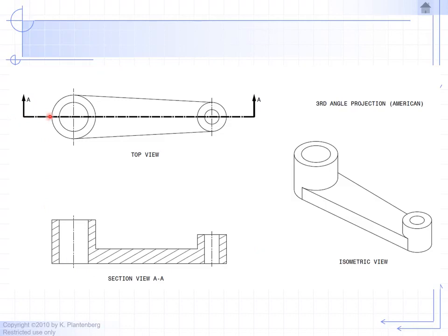And as you're cutting through the top view, here you're cutting through the solid, you're cutting through the shaft, and you're going to put hatching lines, which are 0.30 millimeters in thickness. And then when we cut through the hole, this is an opening, this is open space. And we're not cutting through material in this area, so we're not going to leave any teeth marks from the saw blade. So this is open space. We do not use any hatching in the open area.